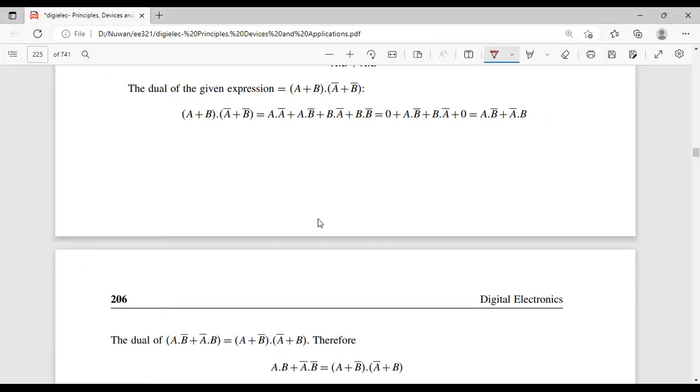You are asked to design a counter that can count from 1 to 5 like this. So you have to count 1 to 5. How many bits do we have to use? We have to use 3 bits, no? So we have to use 3 bits here.